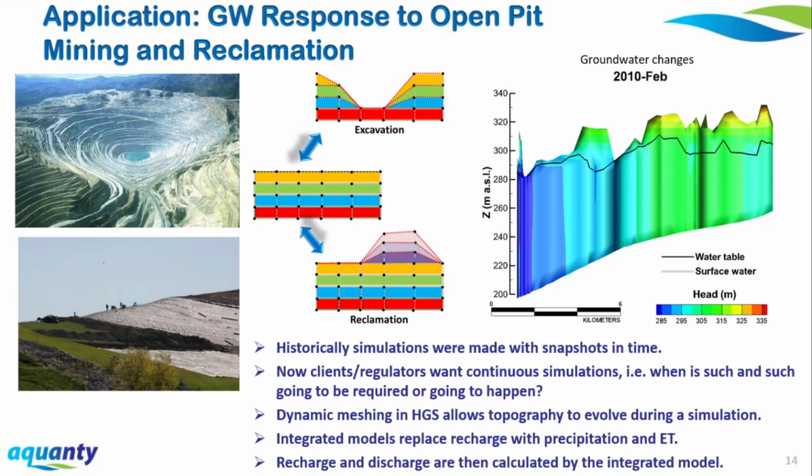By definition, conjunctive surface water groundwater use motivates simultaneous simulation of both extractions and additions, either through injection wells or surface applications such as ponding or irrigation. So this sort of water movement is easy to implement in an integrated model, and you can then observe the interactive effects between the different water sources.